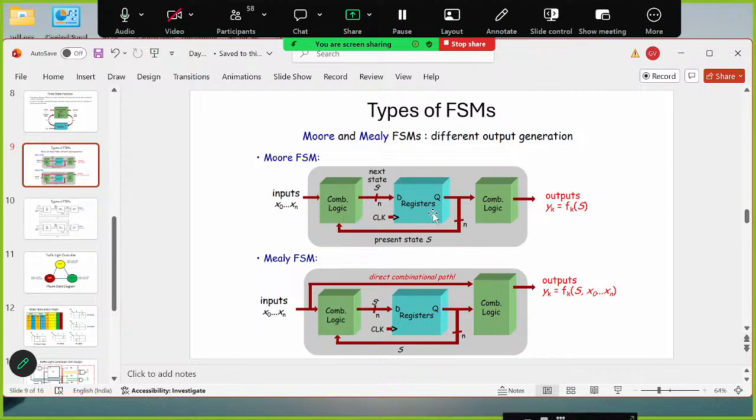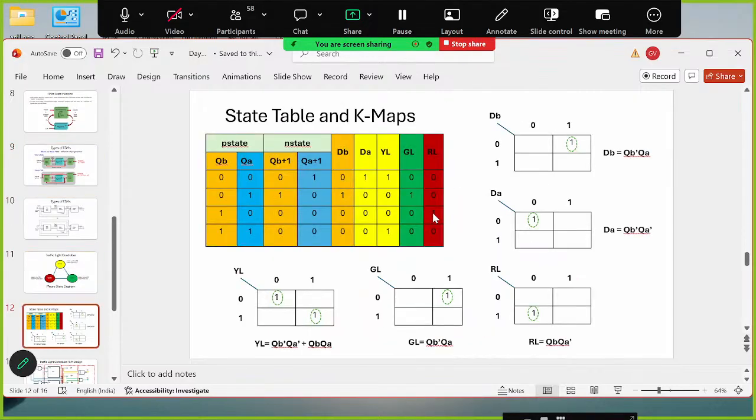But depending upon the scenario given in the question or as per the requirement, you can choose your flip-flop and try to map the present and next state situation with the transition table of the particular flip-flop.